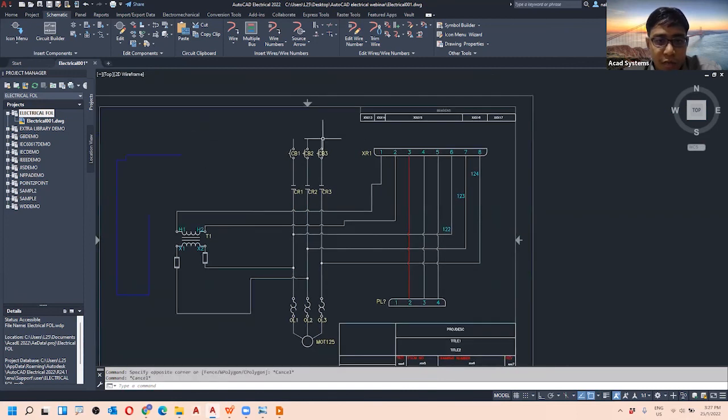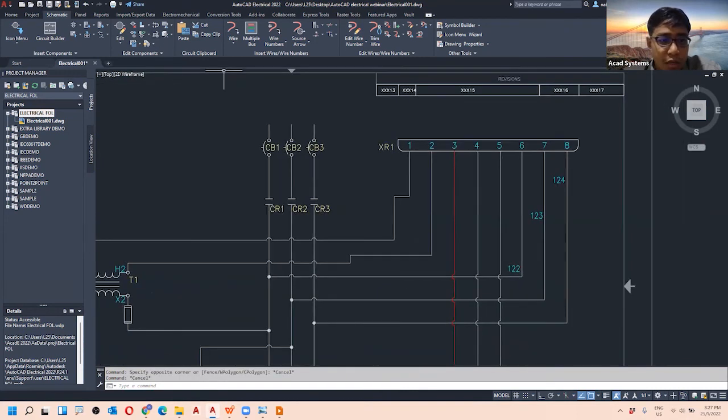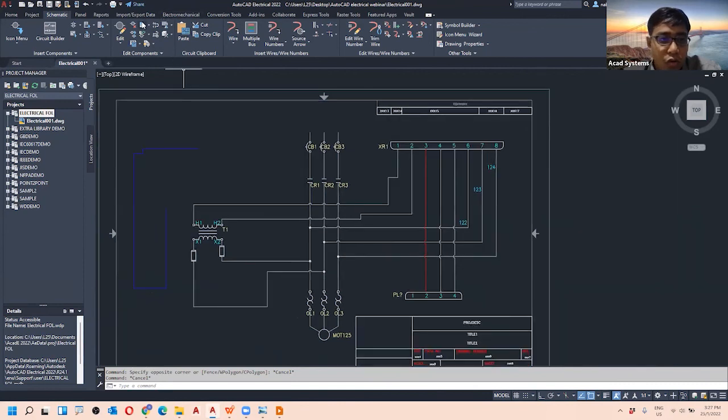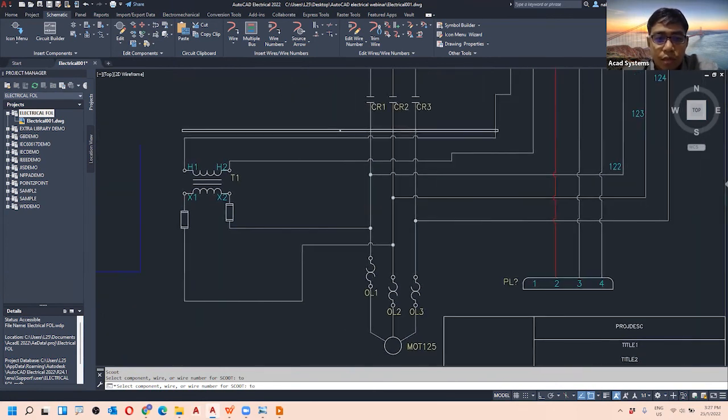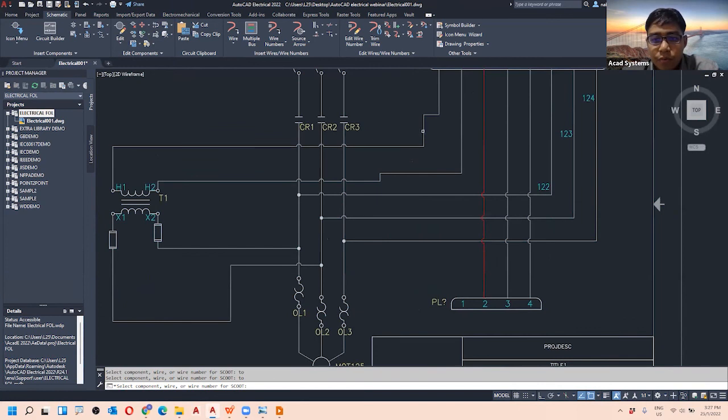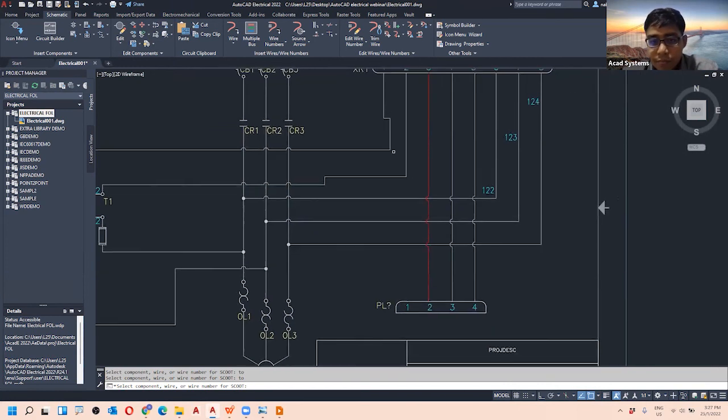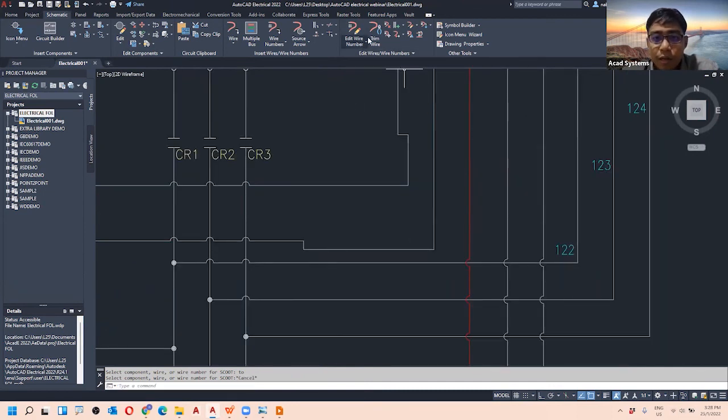If you like to move this wire also, you can also use some of these tools. For example, I have scoops. Not only that you can select and move, you can scoop basically your icon menu, your components. You can also use this scoop to basically move your lines, and it will automatically update it for you. Now I can start to manage and create my wires a little bit better.